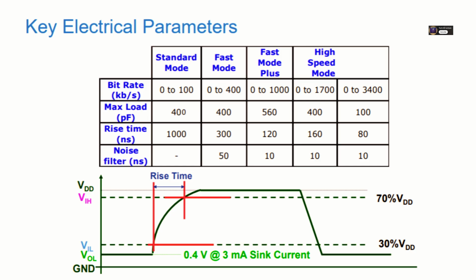Bus capacitance comes from the physical wiring. Longer cables add capacitance. It also comes from the input pins of all the devices connected to the bus, and even the PCB traces themselves. More devices or longer wires mean higher capacitance. And that capacitance acts like, what, a hurdle for the signal?